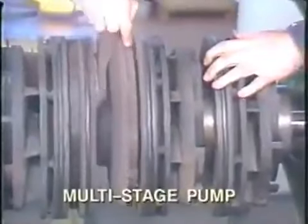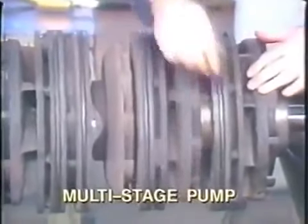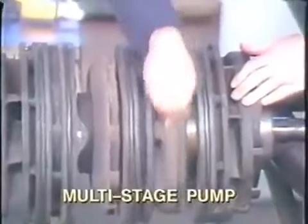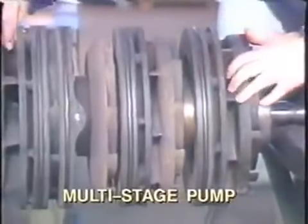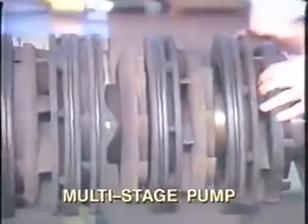A multi-stage pump may be used when higher discharge pressures are required. This pump is like several single-stage pumps operated in series, but the impellers are mounted on a common shaft and enclosed in one casing.